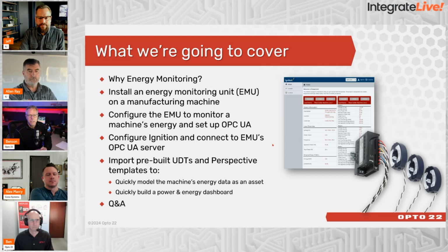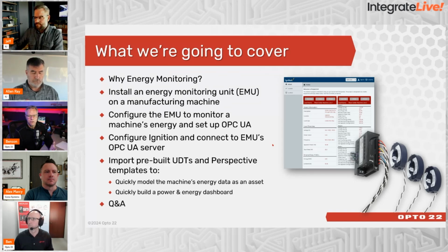Once that's done, and that'll, of course, include configuring OPC UA on that device, then we're going to kick it over to Alex, who's going to actually start to pull up an Ignition server and start connecting to that EMU through OPC, and use some really cool tools that Alex and his team developed that include both Perspective templates and a UDT to quickly and effectively dashboard this information.